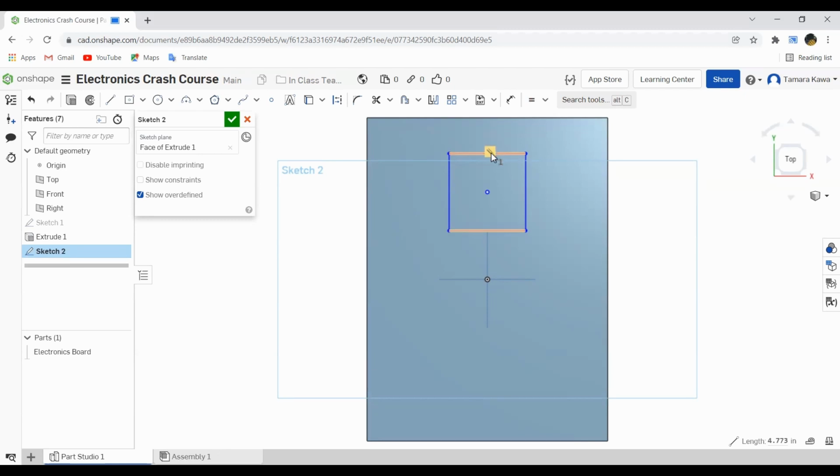All right, so you'll notice that when I hover over some of these lines, various constraints will show up. And you'll also notice that I can have 2 lines selected at once without having to hold down Alt. So be careful about doing that when you're in Onshape. It will sort of automatically select everything that you click on. And if you're trying to edit a specific feature and you have something else selected, you might not be aware of it.